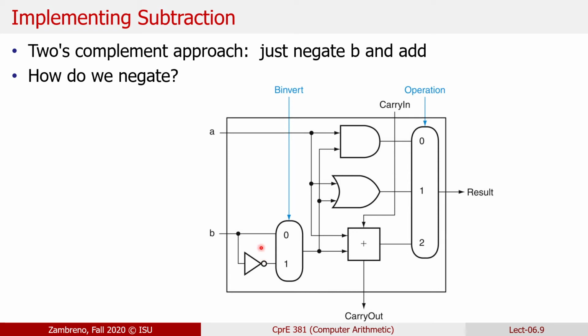To support that operator of subtraction, you would do so via negating B to get the 1's complement, and then adding that +1 to your design to make it a 2's complement. And then you wind up with A plus negative B to get your A minus B result. This does give the impression that it's an entirely separate control input.